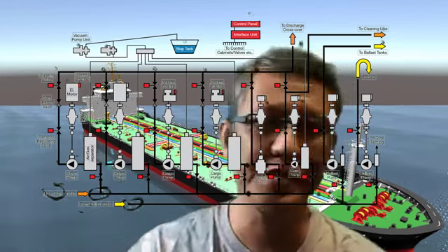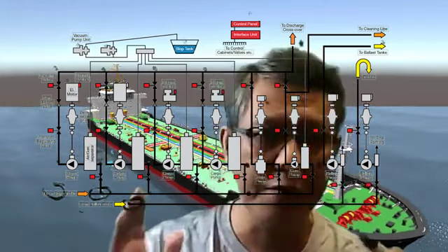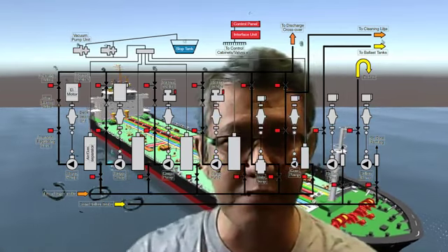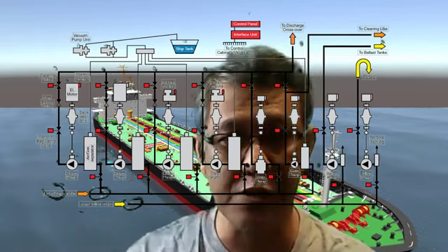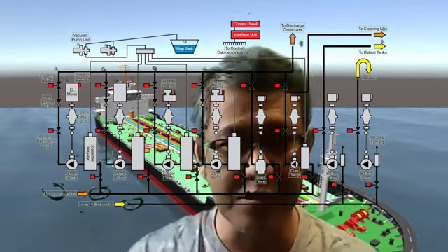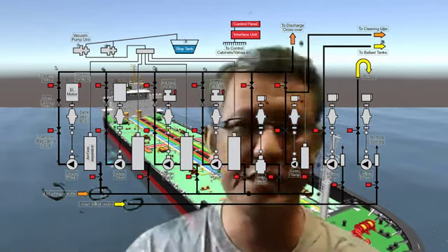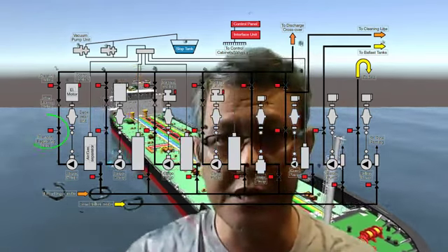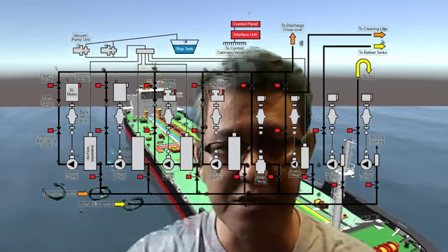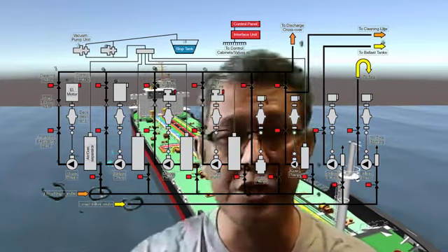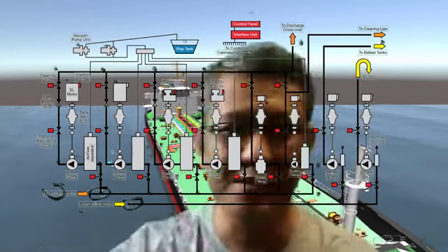There are cases where the chief officer will do it manually because they can actually feel how the pumps behave at the same time. Sometimes there are also differences wherein a computer is monitoring compared to a human doing the control. So in this case, controlling the so-called regulating discharge valve is also important, especially when your pumps and systems are old. In most cases, the performance of the system is somewhat deteriorated already.